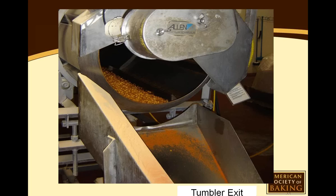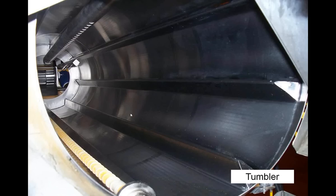Here on the tumbler exit, again, a couple of pretty big call-outs. We can look at fasteners, and we talked about that before. Note the wing nuts, exposed threads, drive units over exposed product, stitch welds, and if you look at the exit chute, a large surface area that probably is stationary and not able to be moved at the exit end of the tumbler. And if you look at the tumbler itself, how would you clean that overhead spray bar?